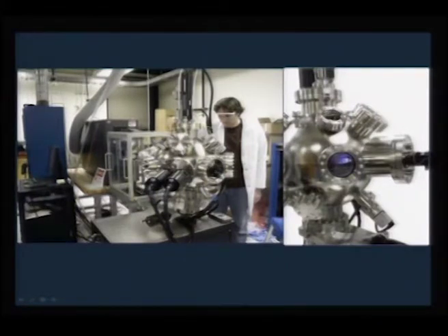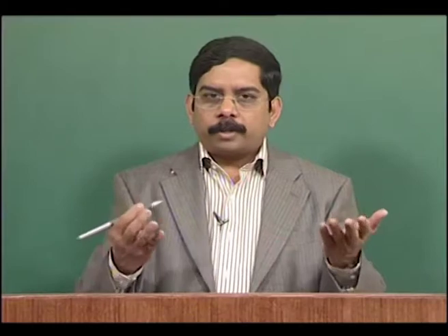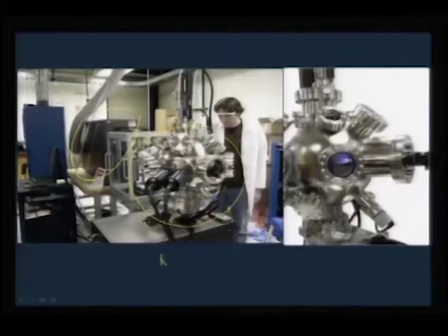This is the vacuum chamber as you see here, and at the rear side you see the excimer laser that is housed, and in between you see these glass windows, mainly to shield from the radiation, because what you are pumping is actually UV radiation from excited krypton fluoride, and this is giving UV radiation of 248 nanometer wavelength. Because you are using ultraviolet radiation, it is important that you shield it.